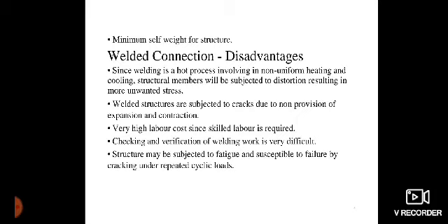So, welded connection disadvantages. Since welding is a hot process involving non-uniform heating and cooling, structural members will be subjected to distortion, resulting in more unwanted stress. Welded structures are subjected to cracks due to non-provision of expansion and contraction. Very high labor costs, since skilled labor is required.